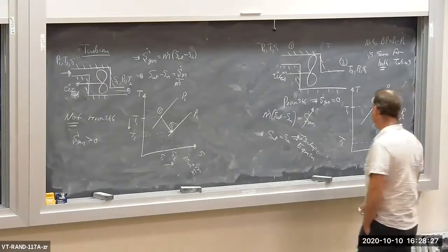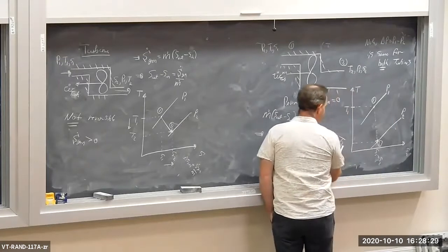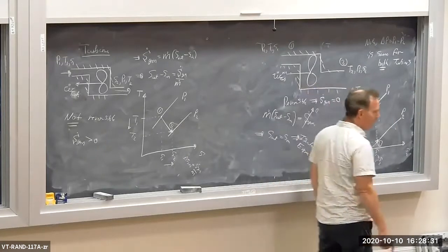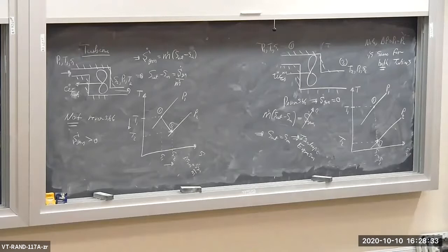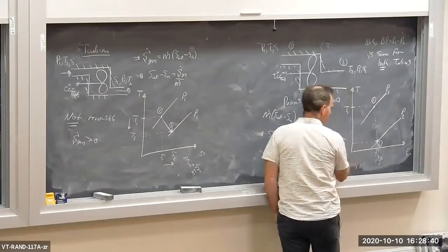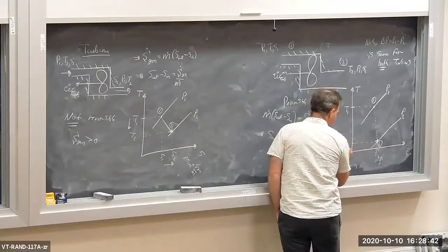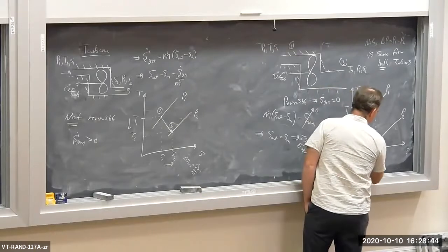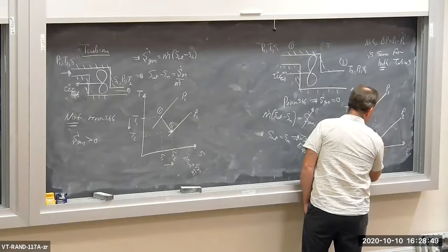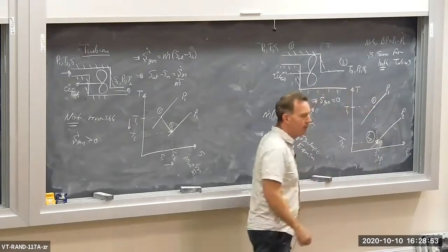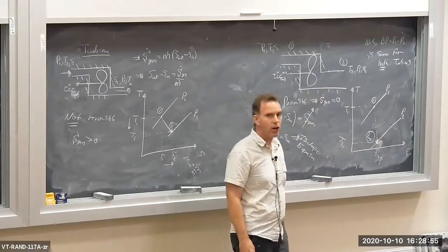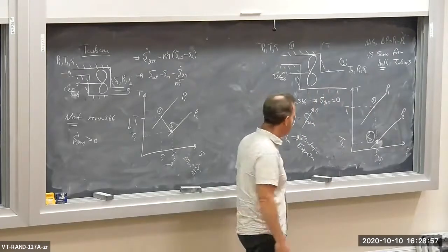By the way, this state 2 is kind of a special state. It's the state for an isentropic expansion. So I'm going to put a little s right after the subscript 2, and I'm going to call this state 2 sub s, and put a circle around it. 2 sub s means the constant entropy process.